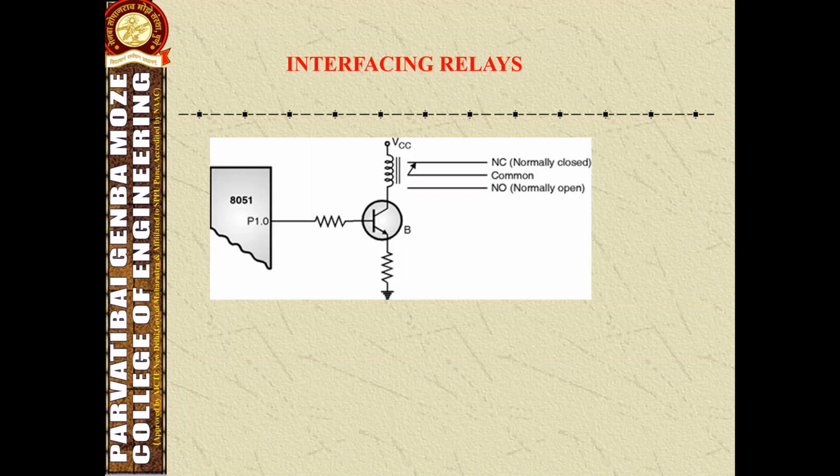The armature is linked to the yoke and mechanically linked to the moving contact or contacts. It is held in place by the spring so that when the relay is de-energized, there is an air gap in the magnetic circuit. In this condition, one of the two sets of contacts in the relay is closed and the other set is open. When an electrical current is passed through the coil, the resulting magnetic field attracts the armature and consequent movement of the movable contact breaks a connection with the fixed contact and makes a connection with the other contacts.